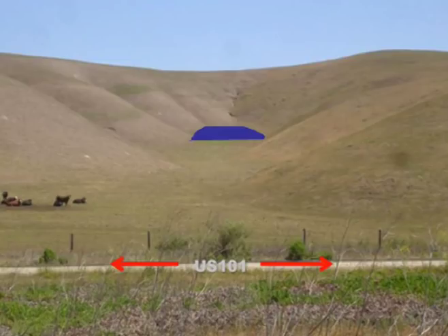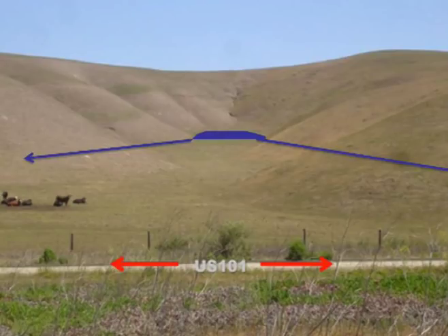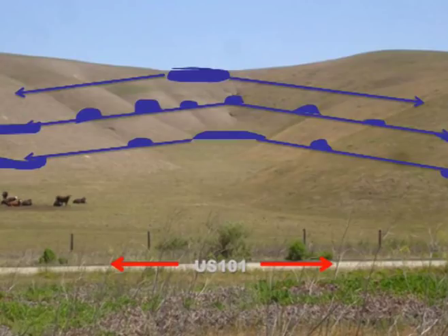Well, then, probably the single most significant innovation that I've done with the whole Keyline process is, instead of just running a line that's perfectly on contour from the key point, right off the bat, if I can, I'll pitch that slope 1%. So it'll be going out 100 feet and dropping 1 foot. And that right there has solved 98% of all of the challenges that I've come up with the whole Keyline system. Once you do that, 98% of the time, when you start doing these parallels up and down, all those parallels, for the most part, will pitch towards the ridges.